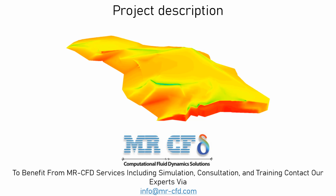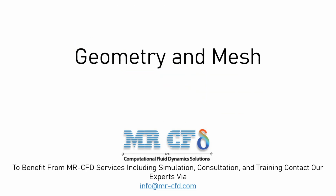In this project, the air enters the fluid domain with a velocity and temperature of 8 meters per second and 297.5 Kelvin respectively. The energy model is activated due to the nature of the flow, which is of the external flow type, and considering the airflow velocity, which has consequences such as flow separation and vortices behind the mountain, the K-epsilon Standard model has been used to analyze the turbulent flow.